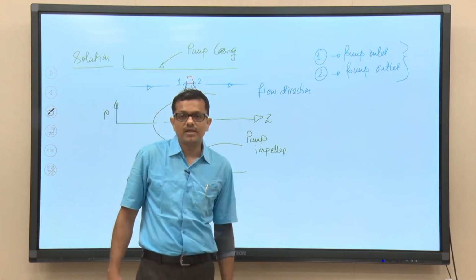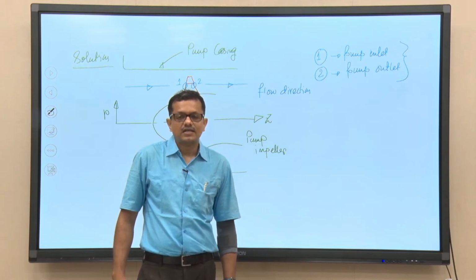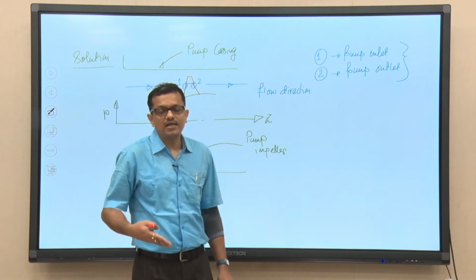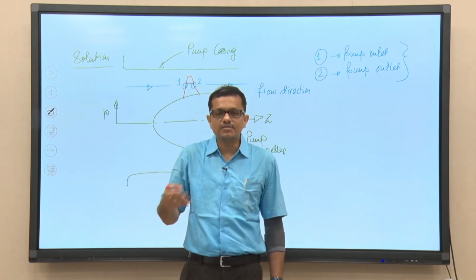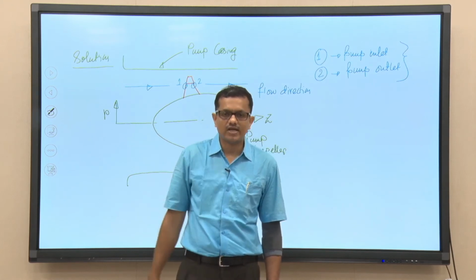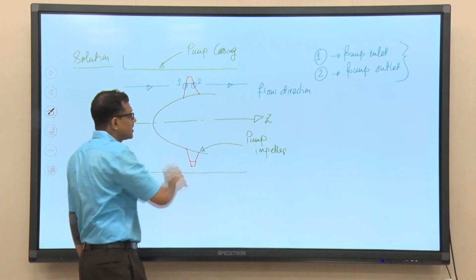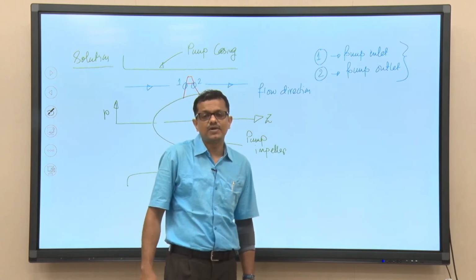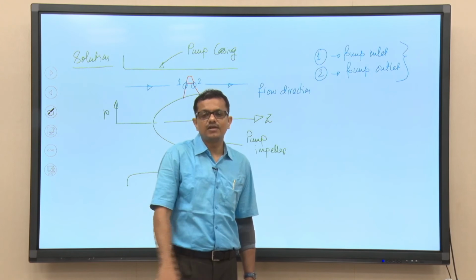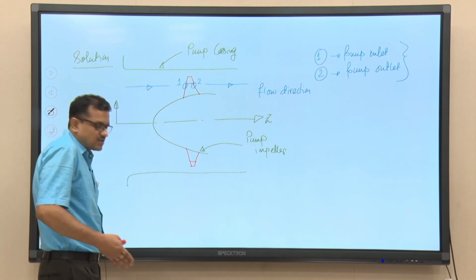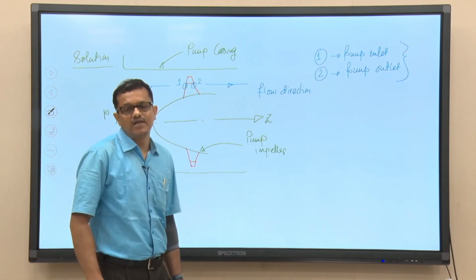We have solved one problem in the context of radial flow pump, and we have seen that sometimes it is explicitly given whether swirl at the inlet should be considered or not. If nothing is mentioned, we will not consider swirl at the inlet. If it is mentioned, that is well and good. For this particular case, again nothing is mentioned about whether inlet swirl we should consider or not, but again I am telling you, in the context of axial flow pump we should consider swirl at the inlet, and if it is mentioned that it is swirl free flow, then definitely we may ignore it, fine.